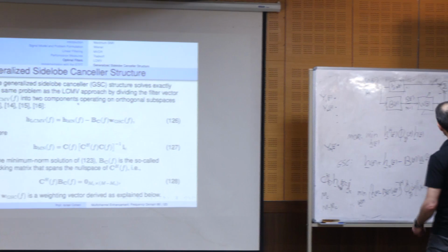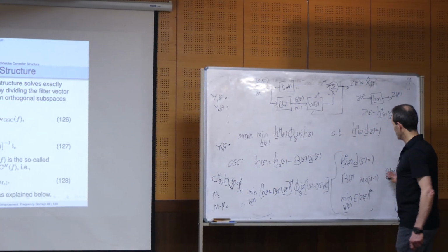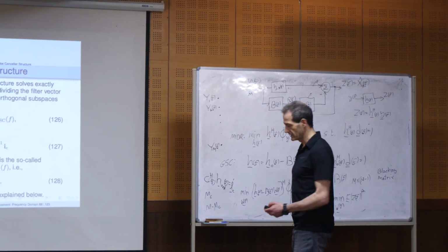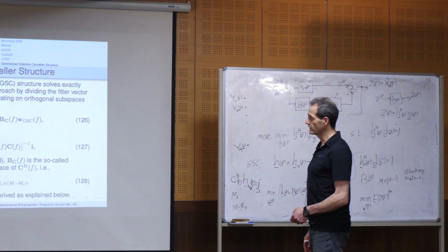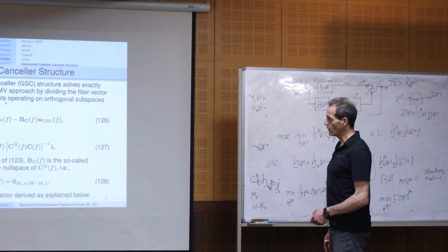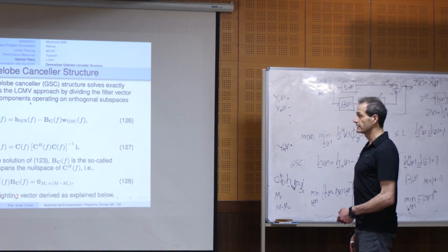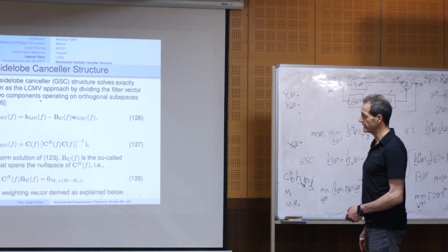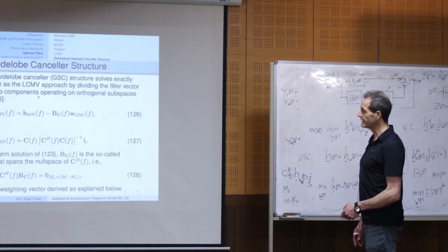You see, in this case, in the MVDR, it was what we wrote before, okay? So it's a blocking matrix. We showed an example how to block the desired signal. So actually, if we know the steering vectors of the constraints, so we know the matrix C, we can find a blocking matrix of size M by M minus MC such that this will be satisfied.